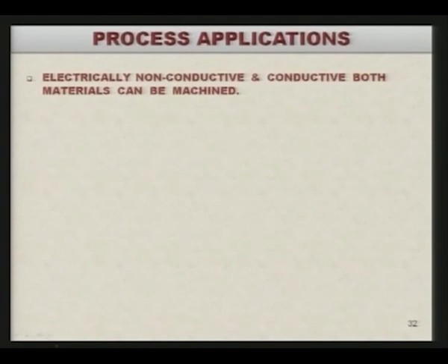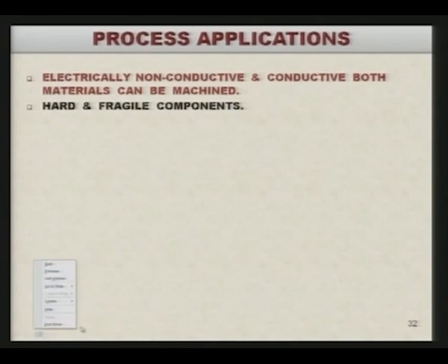It can be applied for electrically non-conductive material as well as conductive material, because we are not making either tool or workpiece as cathode or anode. It is very good for the hard and fragile components, or the components made of hard and fragile materials.